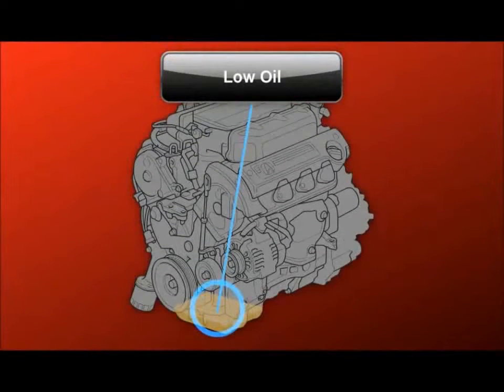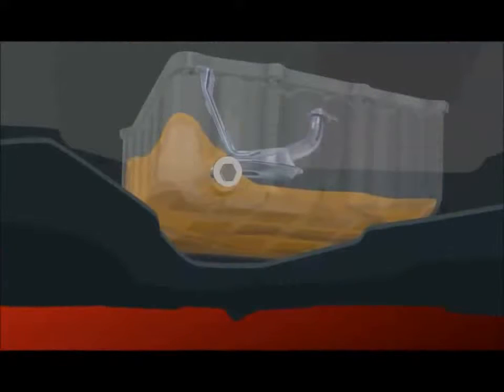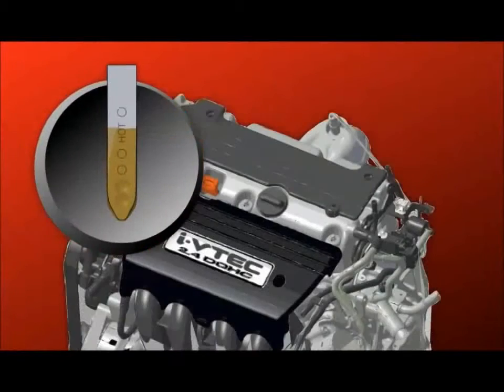Low oil level causes different symptoms. Hard braking or cornering can expose the oil pickup, drawing air into the oil pump and dropping system pressure. A low oil fill also reduces the system's ability to dissipate heat, increasing overall crankcase temperatures. For all of these reasons, always check the engine oil level before further troubleshooting.